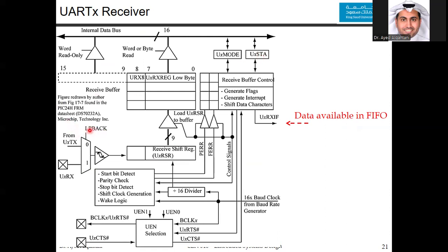And you could actually make a test run using the loopback. So your own microcontroller has the transmitter and the receiver. So you connect the transmitter to the receiver directly without going to an outside receiver. And you use the loopback, so from the internal transmitter of the same microcontroller. And you could use something from the outside. This is always used for testing. So maybe you do the testing first to make sure that everything is fine, and then you do communication with another outside entity.